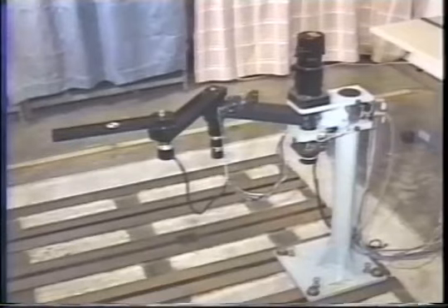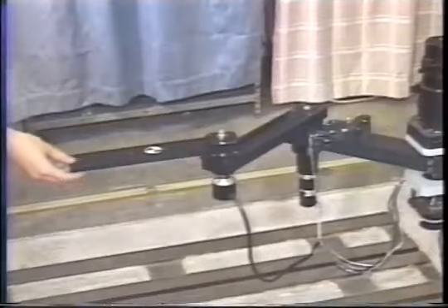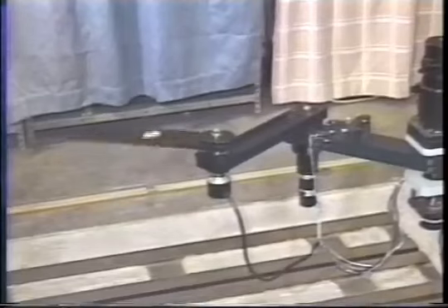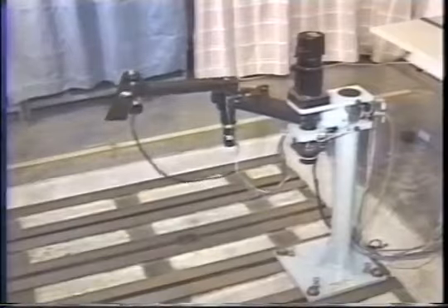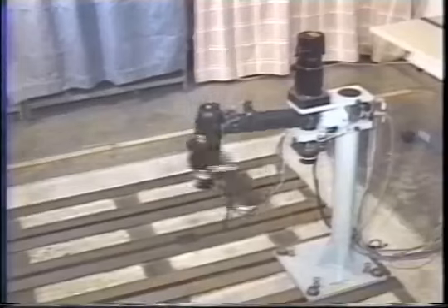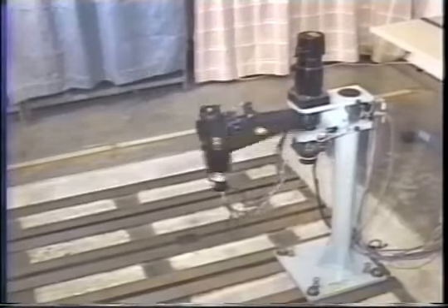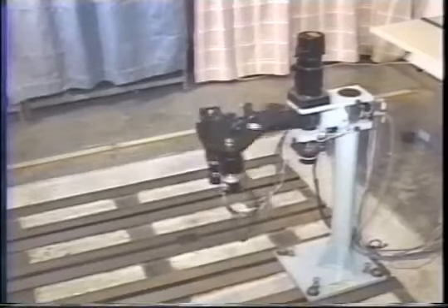Control of a 3 degree of freedom planar under-actuated manipulator is investigated. The manipulator has 2 active joints and 1 passive joint. The dynamic constraint of the free link is a second-order non-holonomic constraint. The objective of the control is to manipulate the position and orientation of the free link using the non-holonomic constraint.